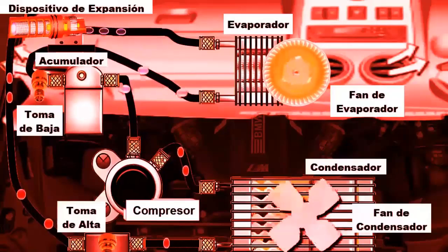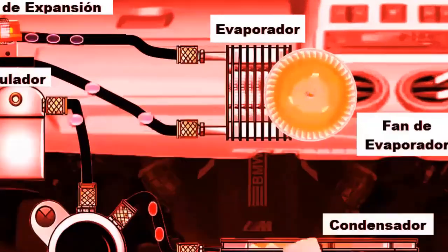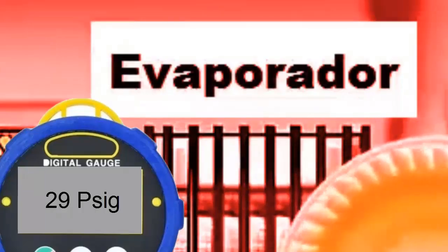4. Frost on evaporator pipes. A slight lack of refrigerant can cause the system to operate with low pressure, which results in temperatures below 0 degrees Celsius, creating frost on the evaporator pipes. This symptom indicates that the system needs a minor gas recharge.